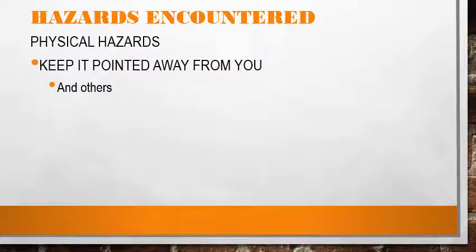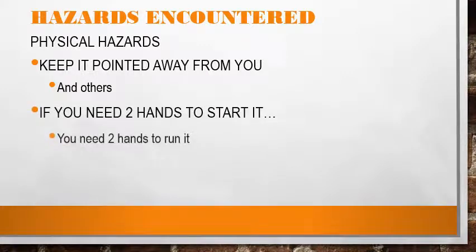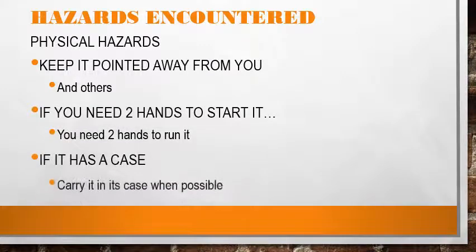If it has a sharp blade or a sharp end, always make sure you keep your power tools pointed away from yourself and others. If you need two hands to start the tool, you need two hands on the tool to run it. If it has a case, make sure it's put in its case whenever it's possible.